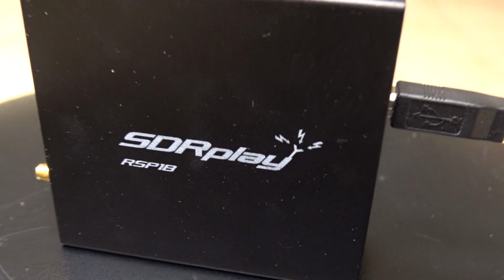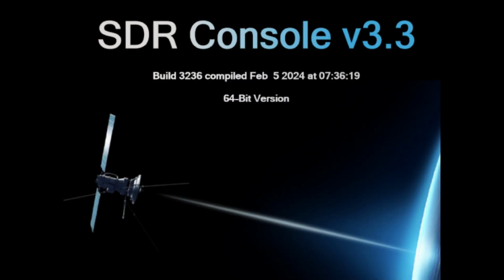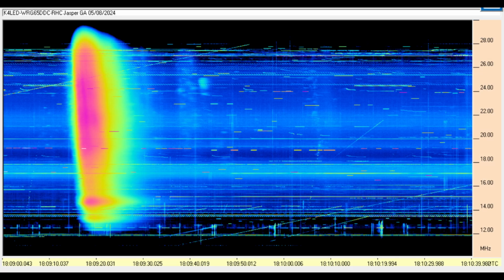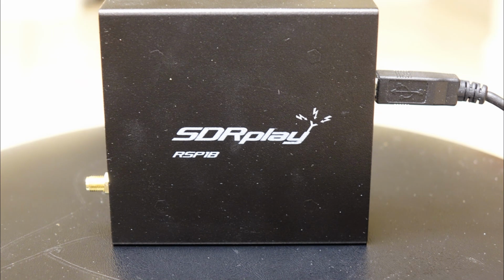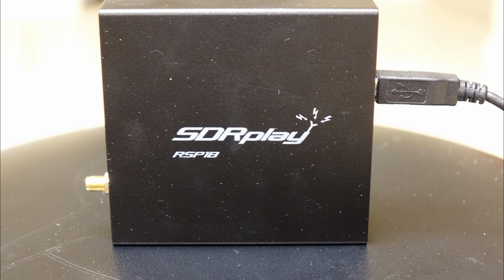This video guide and procedure outline calibrates the RSP1B SDR with SDR Console, the SDR C2 RSS interface program, and Radio Sky Spectrograph software. The RSP1B numerical menu settings suggested in this video apply only to SDR Console and SDR C2 RSS. The actual calibrated settings apply to this one specific RSP1B SDR. Your RSP1B may require slightly different settings to be classified as calibrated. This video aims to provide a general outline of the calibration procedure.